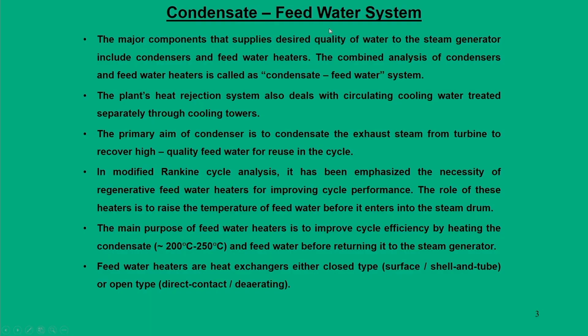So, let us start with this concept of condenser and feed water systems. We discussed this concept in our previous lectures, where in a condensate feed water system, the condenser plays a dominant role, and during this condensation process, the steam from the turbine exit loses heat and condenses to liquid water.